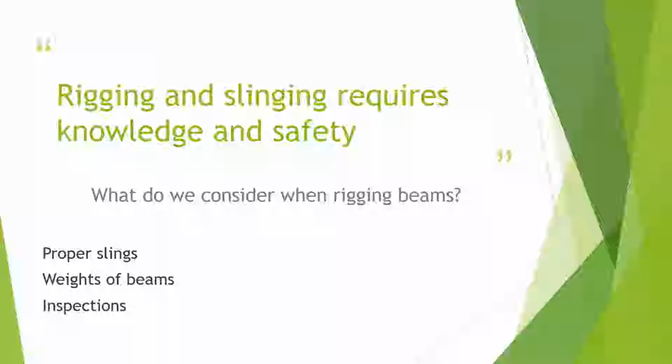Inspections of those slings are also very important. During the inspection, we're going to find anything that could cause that sling to possibly break or bust, which would mean we would have to take it out of service. And if it passes inspection, we're good to go. Always important to do those inspections.